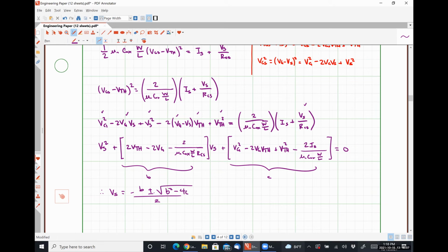Effectively, we're going to get 2 solutions to this, one of which will make the transistor operate in saturation and the other of which will not. We would have to use the one that keeps the transistor in saturation to figure out if we're biasing this thing correctly. Okay. So that practical current source there does add quite a bit of kerfuffle to our analysis here. Fortunately for us, it's much less of a pain in the butt when we're looking at our small signal model.